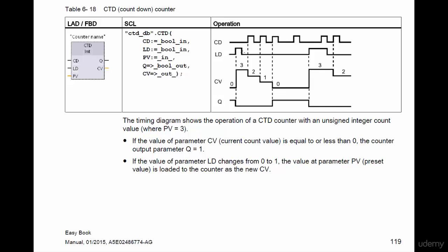When we switch off this signal, then on each counting down signal this value is decremented by one, up to the value 0. When we have got value 0, you see that the output of the counter is in high signal, because this signal is equal to 1 when the counted value is equal to 0.